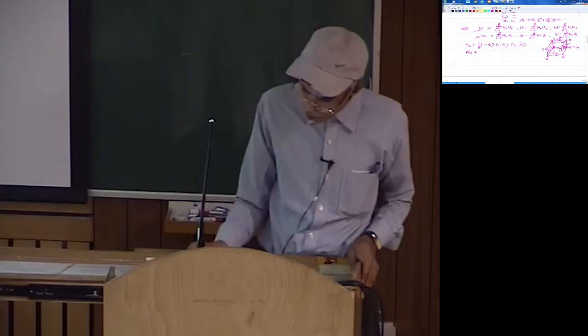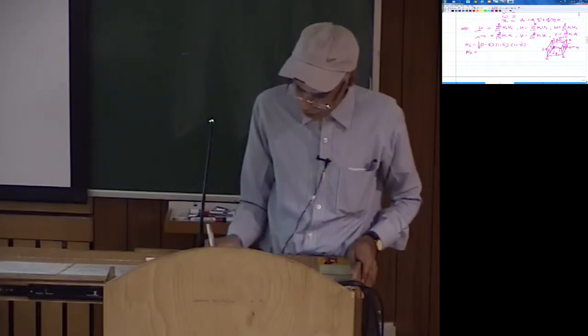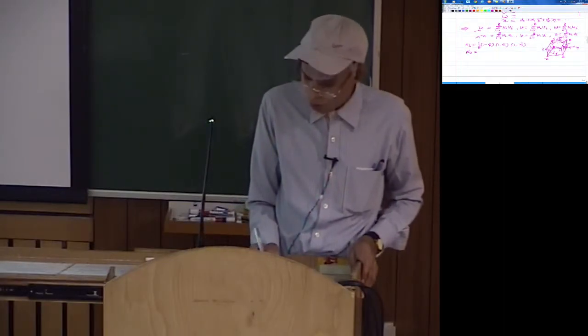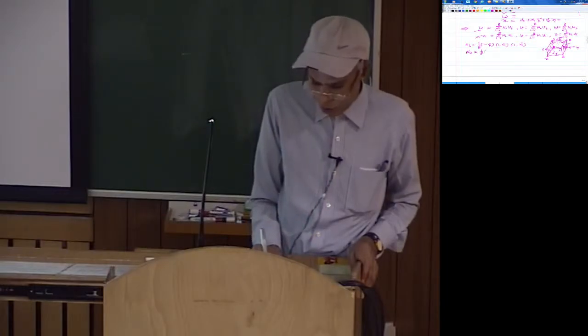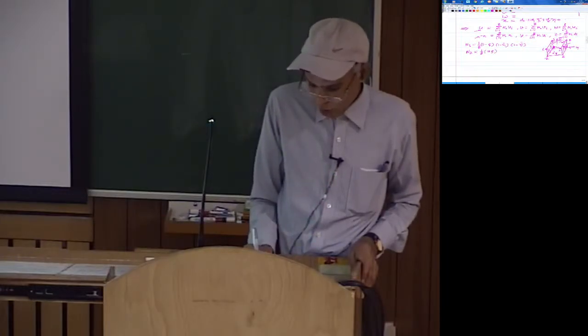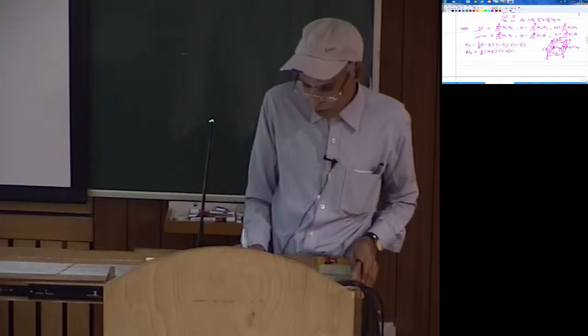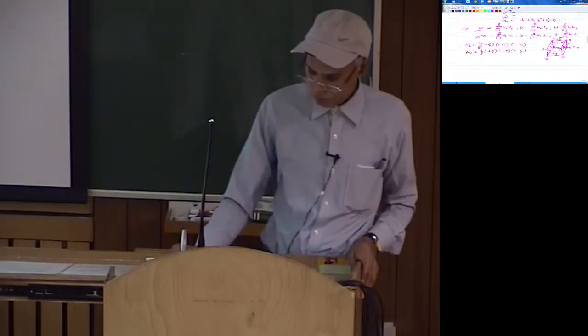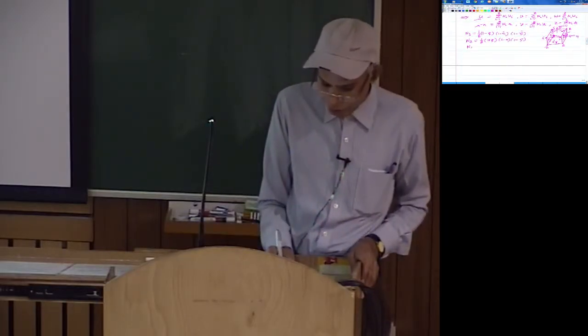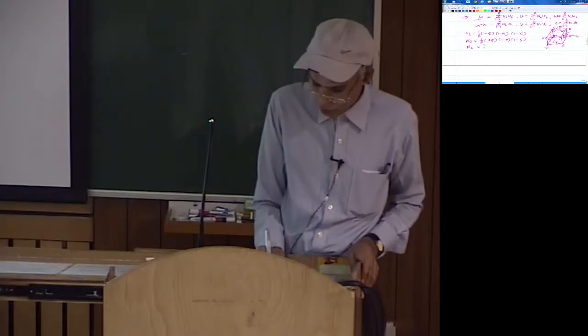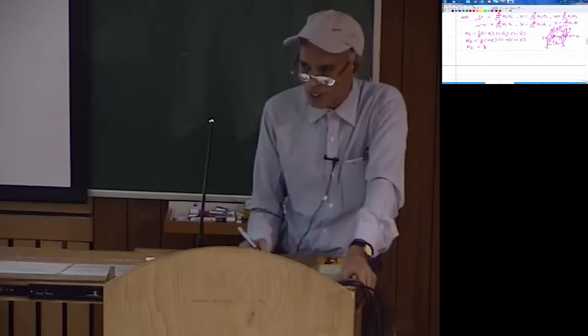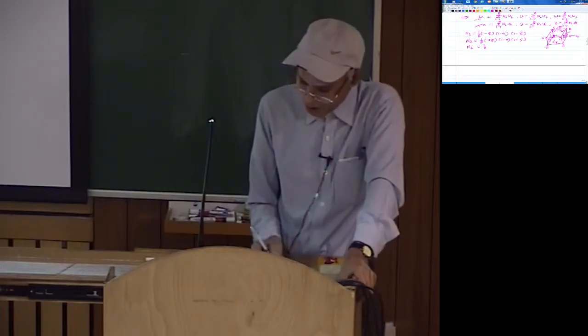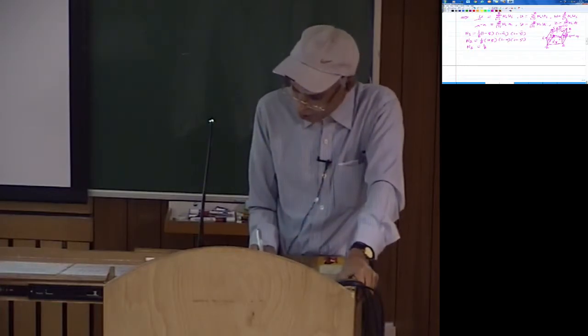The only change is in the equation of the back side, where we replace 1 minus xi by 1 plus xi. So this would be 1 plus xi, 1 minus eta, 1 minus zeta. In the same way you can write all the other shape functions, with the factor 1 by 8. There is a standard format for this, so we shouldn't spend more time on it.